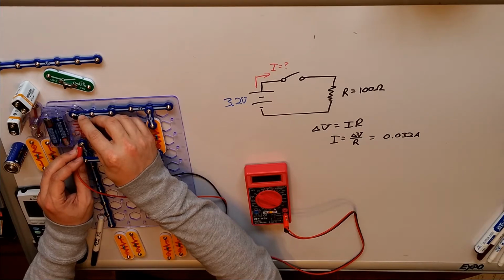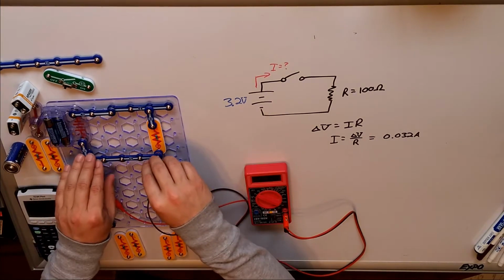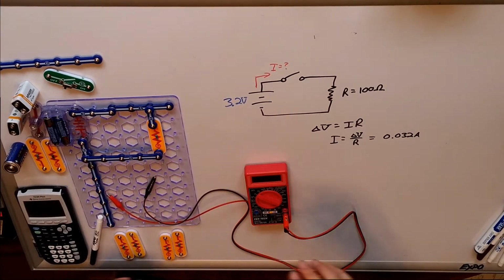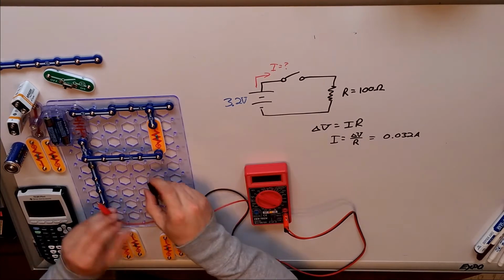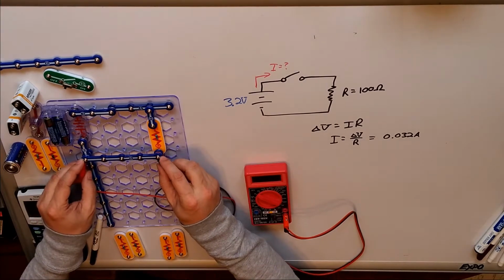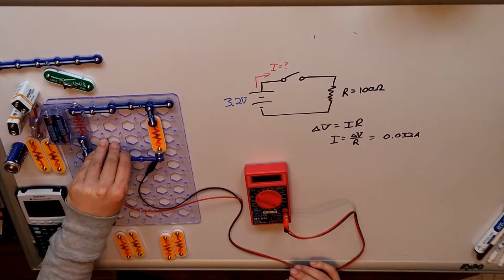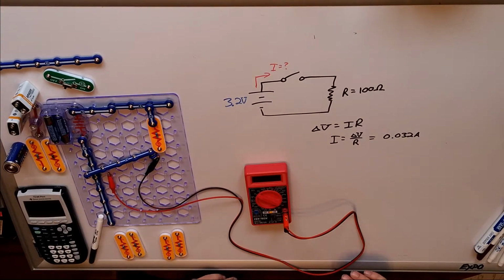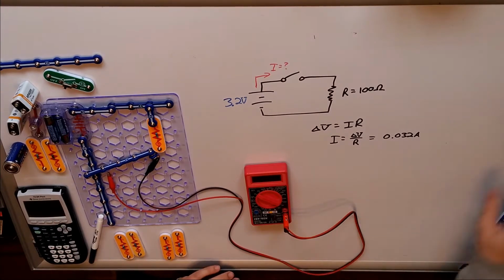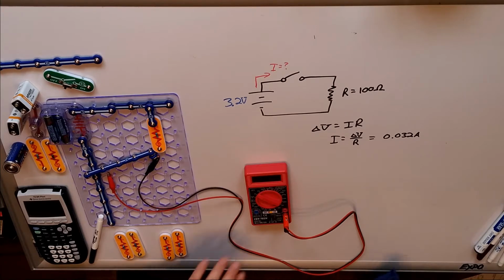We can see that it drops a little bit. It's actually 3.1 volts. These wires are also, in real life, going to have a little bit of resistance of their own. In fact, I could check right here. That's not seeing anything. I'd probably have to bump it down some. That being said, we probably got a little bit of resistance. In real life, these numbers are going to fluctuate just a little bit, but we still get a pretty good value for what we're dealing with.